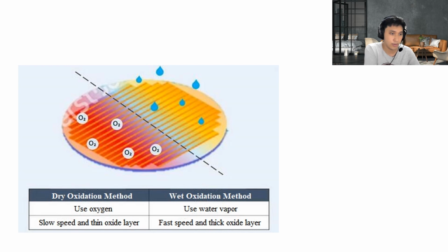In addition to the oxidizer, there are other variables that affect the thickness of the silicon dioxide layer. First of all, the wafer structure, surface defects, and the internal doping concentration will affect the rate of formation of the oxide layer. In addition, the higher the pressure and temperature generated by the oxidation equipment, the faster the oxide layer will be formed.